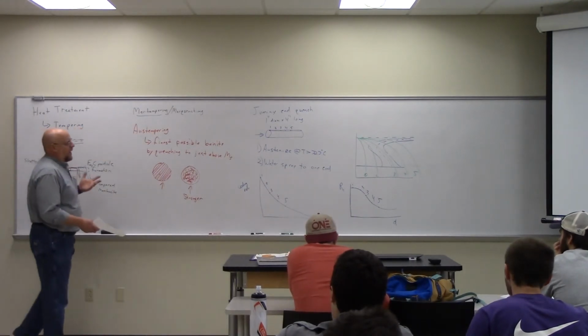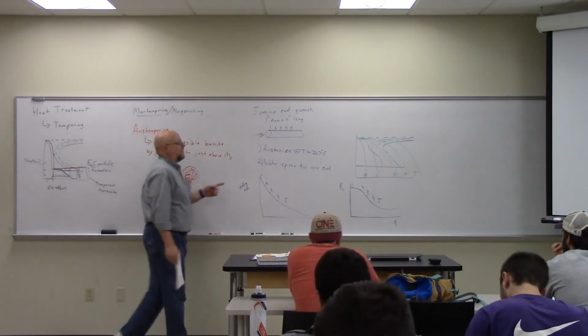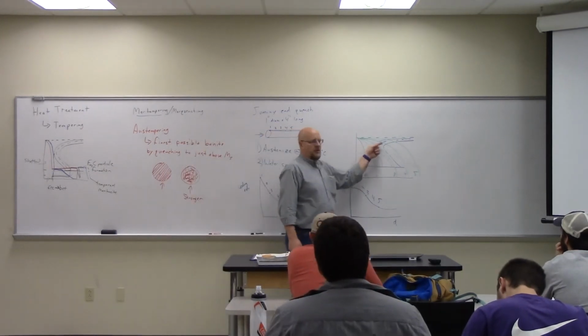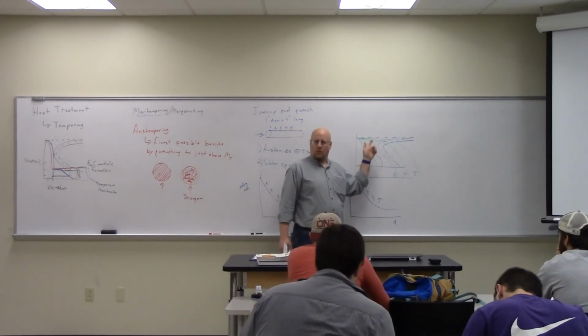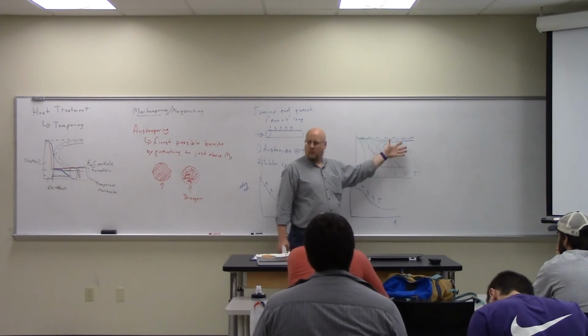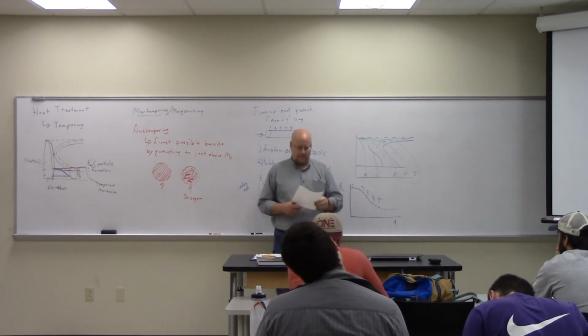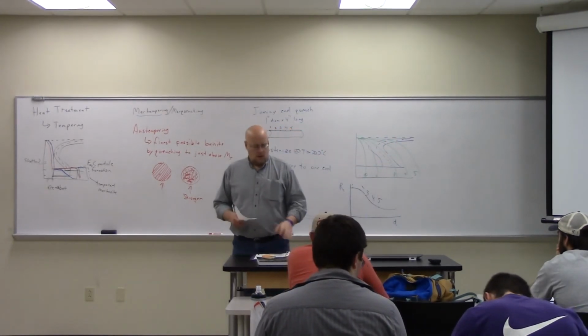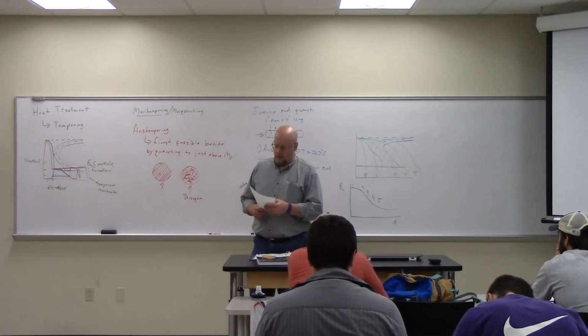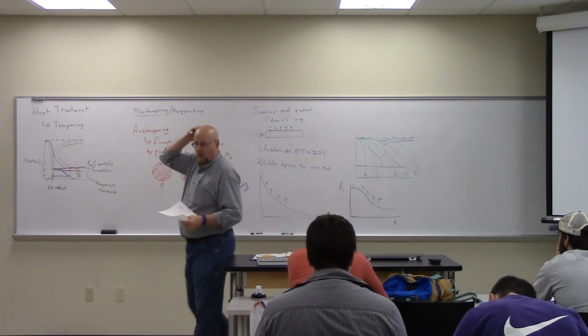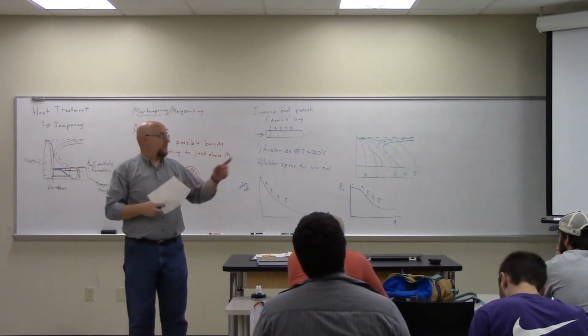And then you can do actual microstructural analysis to go in and look at each one of these samples and see what the microstructure looks like, to see what's a coarse pearlite, what's a fine pearlite, all that kind of stuff. Okay. So there's one more kind of hardening that we haven't really talked about here. This is all using eutectoidal compositions.